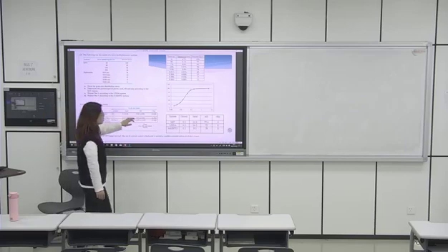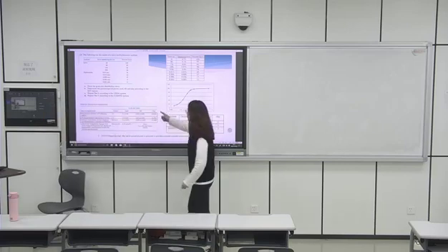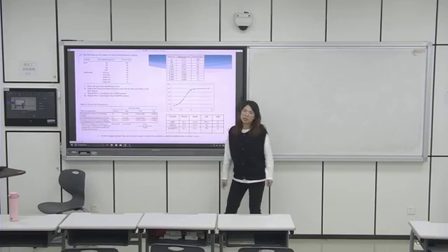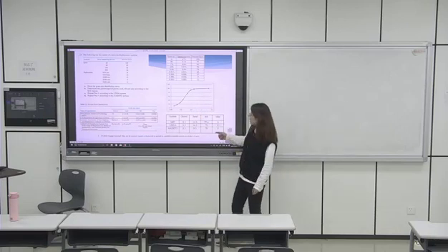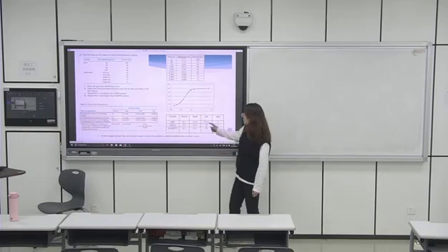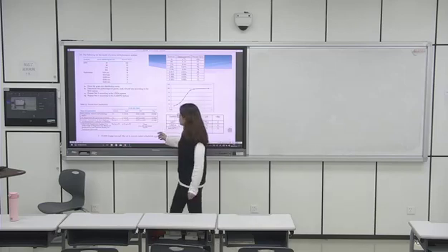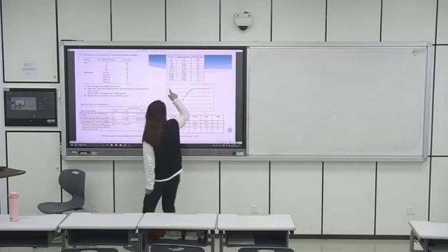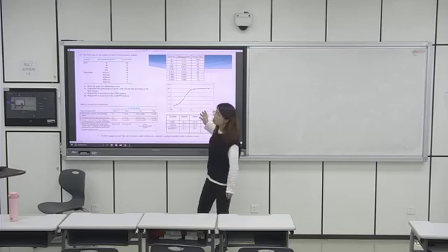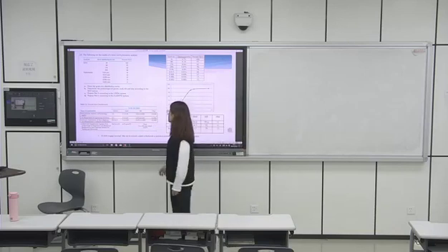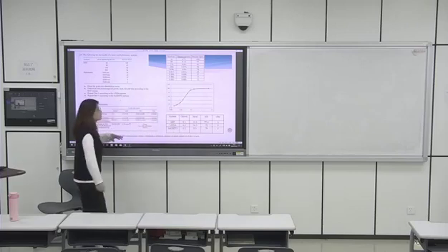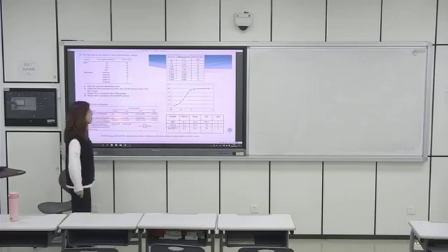And finally, for example, for clay, the definition in the three systems is the same, so the clay percentage is the same. The silt is different, but not a huge difference. Sand and gravel are the same, because for this kind of soil, there is no particle larger than 10 millimeter. So actually, for this soil, the results are similar.